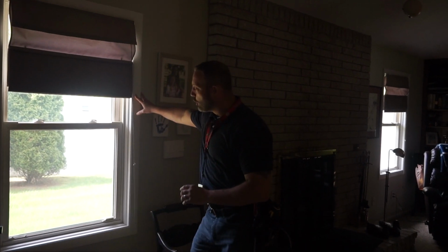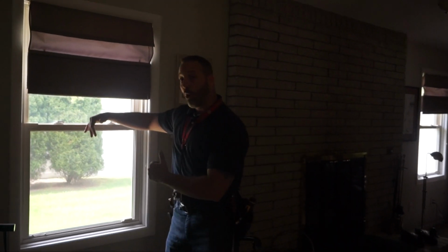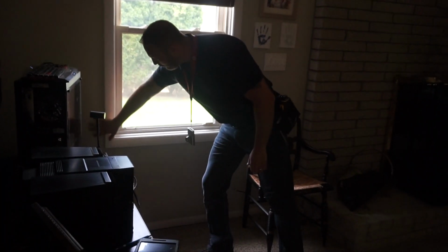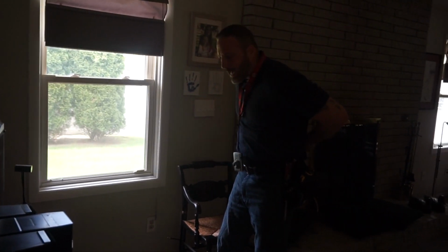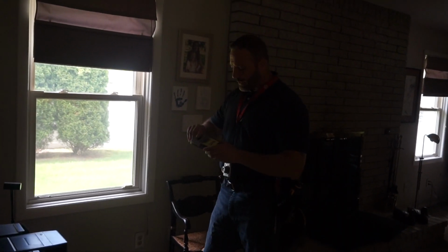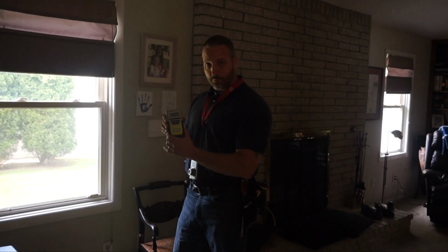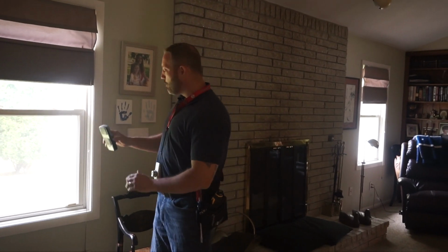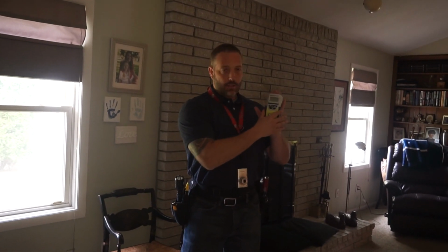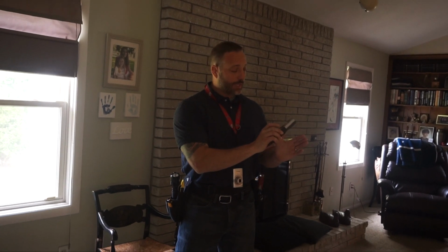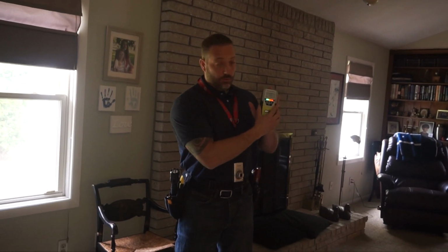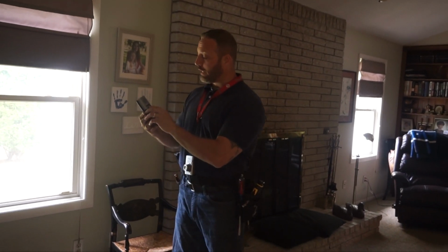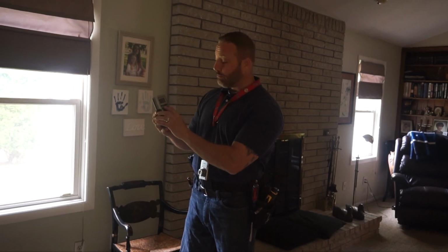Next, you want to take a second look around the window, because it is an opening in the wall. You want to make sure there's no staining around the window, and if there is any staining, what we want to do is have our moisture meter. This is a pinless moisture meter, and if we have a stain, what you would end up doing is showing everybody, one, that it's operating, and that because we're all made of water, we can see how the system is working. Secondly, you want to make sure you have it on sheetrock, because there's different modes.